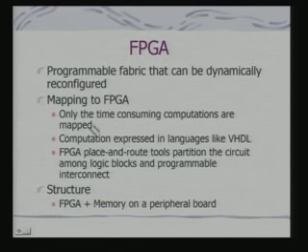And typically the structure of this kind of FPGA based board is FPGA plus memory on a peripheral board. This memory can have the data which is used by the computation that the FPGA is expected to do. In fact, you can get FPGAs in various forms. Some FPGAs can be programmed only once. So, once it is programmed, it cannot be changed. There are other FPGAs which are reprogrammable, which can form the reconfigurable component in a platform.